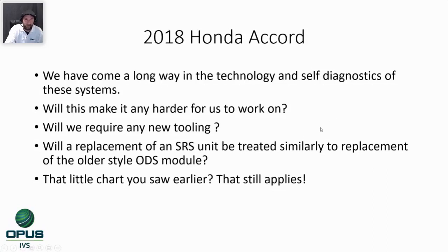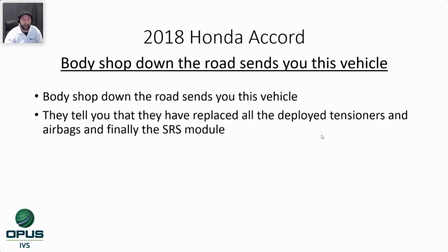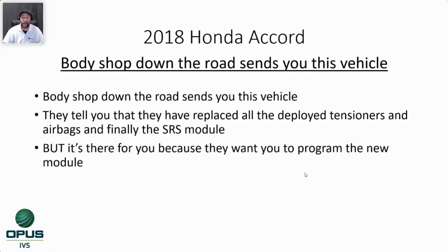If you follow that chart and look at whatever module you're replacing or whatever procedure you're going through, it will still be there. It'll tell us what the next step is to complete the process that we're trying to accomplish. So I'm going to give you a little bit of an idea of a case study, without being a real case study. There's a body shop down the road that sends you a vehicle. And they tell you that they've replaced all the deployed tensioners and airbags, and finally they replaced the SRS module. But it's there for you to program the new module.